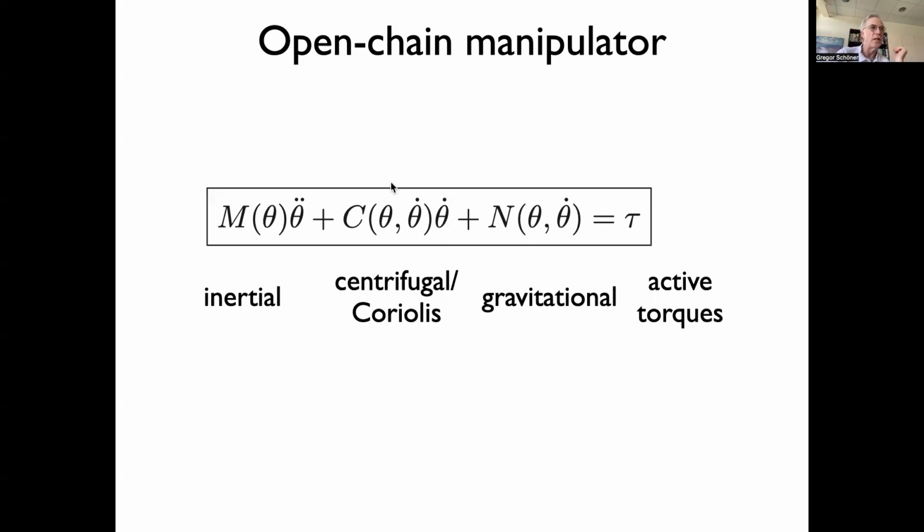And these terms here are really the sources of these kinds of interaction torques. There's actually also a contribution here because this matrix is not diagonal. And so that is a core problem of robotics and actually also of human motor control, that when you send some torque to any of the individual motors that drive the individual joints, these torques have consequences on other joints along the kinematic chain, where they essentially act as a perturbation.